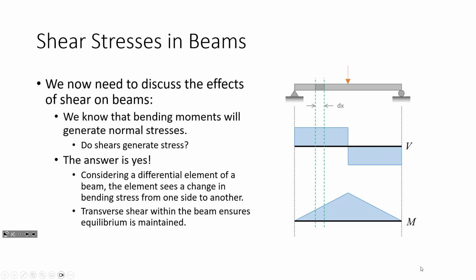No. But here's the thing. Now let's think about this from an engineering mechanics perspective. Did I change the moment of inertia of the beam at all? No, it's still really the same beam. And I would argue I really didn't grossly change the mechanical properties. I mean, this is pretty much wood, just really, really thin strips of it that's been processed. But something about adhering these transverse plies together suddenly changes the stiffness of the element, okay?